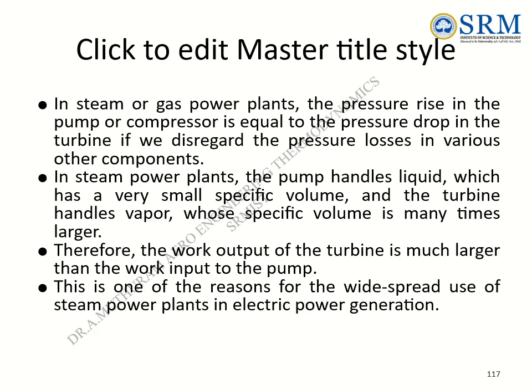In steam or gas power plants, the pressure rise in the pump or compressor is equal to the pressure drop in the turbine if we disregard the pressure losses in various other components. In steam power plants, the pump handles liquid, which has a very small specific volume, and the turbine handles vapor, whose specific volume is many times larger. Therefore, the work output of the turbine is much larger than the work input to the pump. This is one of the reasons for the widespread use of steam power plants in electric power generation.